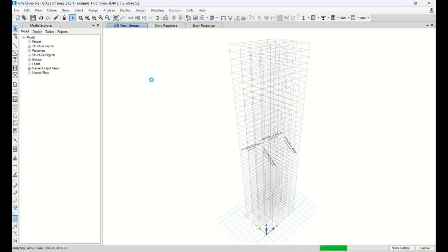So throughout all the load combinations, the dead and superimposed dead load cases are going to be replaced with this construction sequence dead load. We try to avoid the bracing holding up, so we avoid the kind of actual force loss in our column.